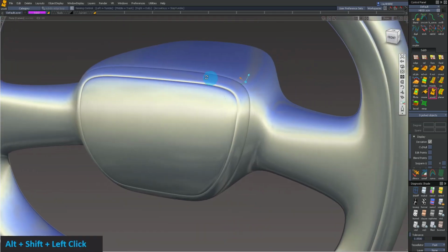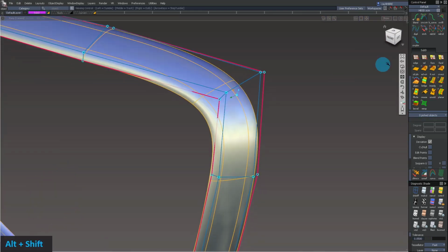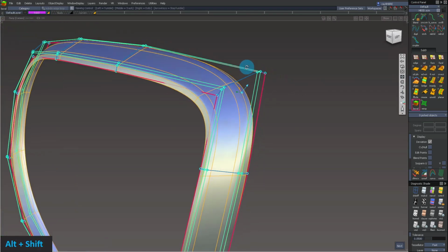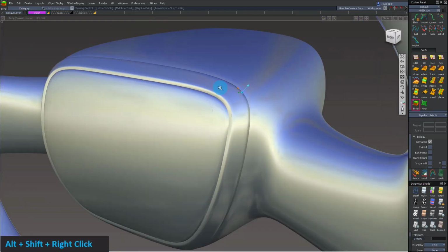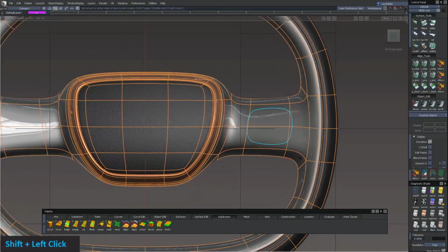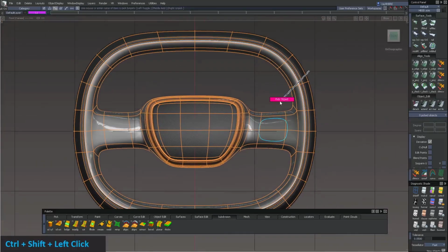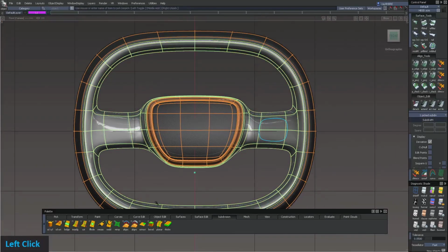And I wanted a tighter core around my frame, so I just got those edges and beveled them again, and that gave me a nice sharp corner there. And once you're happy with the Sub D model, we're going to convert it to a Nurb model to help with all the different tools inside of Alias.